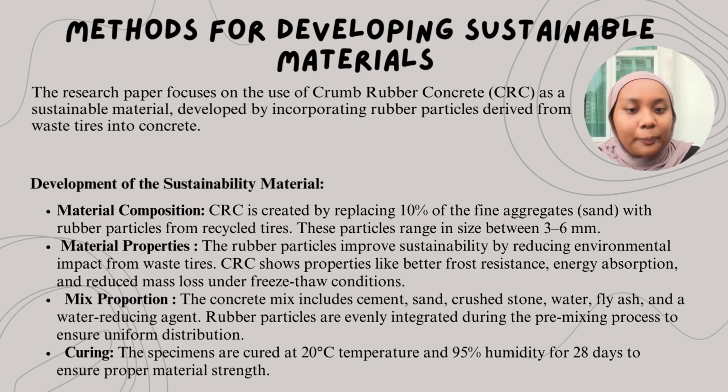CRC shows properties like better frost resistance, energy absorption, and reduced mass loss under freeze-thaw conditions. Number three, mix proportion. The concrete mix includes cement, sand, crushed stone, water, fly ash, and a water-reducing agent. Rubber particles are evenly integrated during the premixing process to ensure uniform distribution.